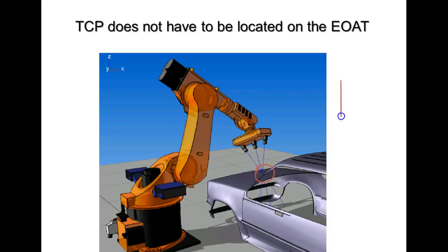On a gripper, all ours use parallel grippers. What am I trying to position? I'm trying to position this point right here. That's the tool center point. So the tool center point on these grippers is never even touched by the tool, because these grippers don't close all the way together. On none of our robots do the grippers actually go all the way. So on ours, this would be the tool center point right here.